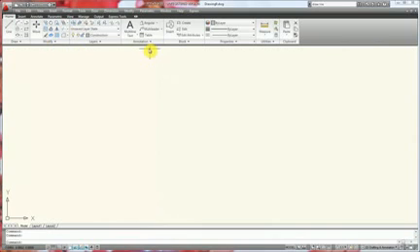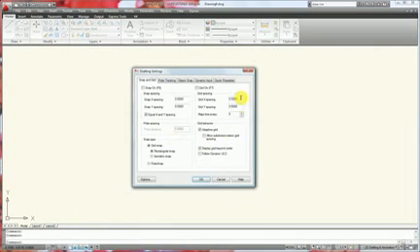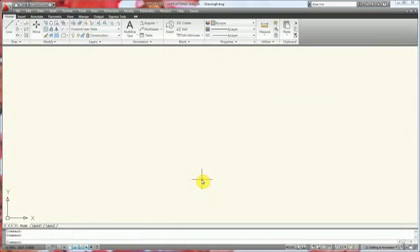Exit out. And the next thing we want to do is set up our object snap. And we're going to set that up to, go to settings. And we're going to set the grid spacing up to 1. Click in the Y spacing and it'll change both of them. Press OK. And the first thing we want to do is make a few construction lines. So we're going to go up to the construction line tool, input V for vertical, and set an arbitrary vertical line. Press spacebar again, and put an H for horizontal. And then we have a point that we're going to go off of now.